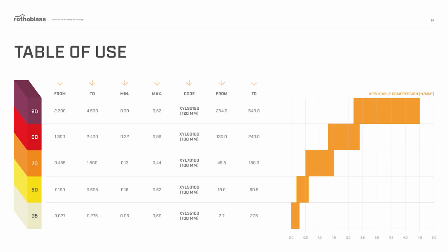These soundproofing strips are defined as resilient materials. They have a function similar to shock absorbers in a car, so you have to choose them according to the load and the frequencies on which you want to isolate the structure. In our catalogues, there are linear load bands recommended according to the different stiffness of the resilient interlayers.